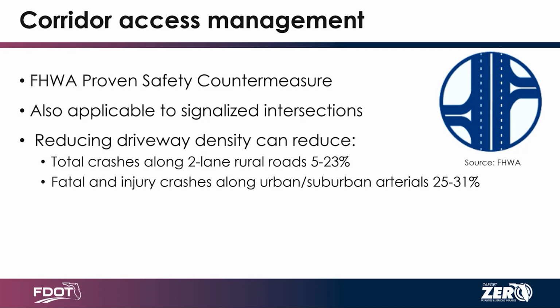So think through whether there is any driveway consolidation that can be done. It also depends on the context of the facility. In more C4, C5, C6 contexts, you're going to have a high frequency of driveways, which may actually reduce speeds. So access management may not be applicable to all corridors and contexts.